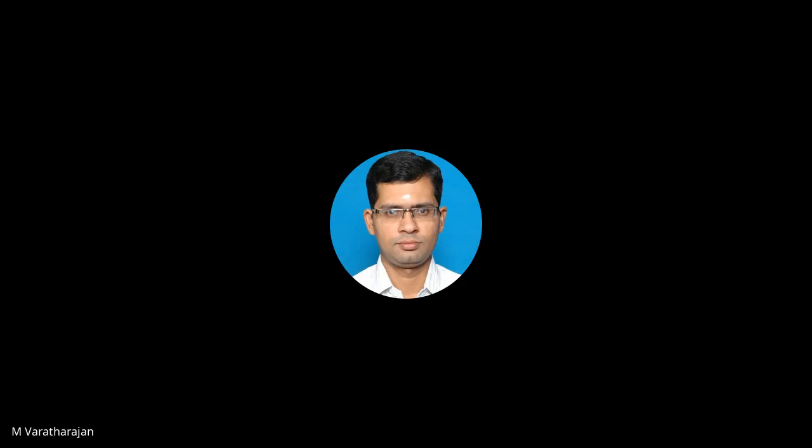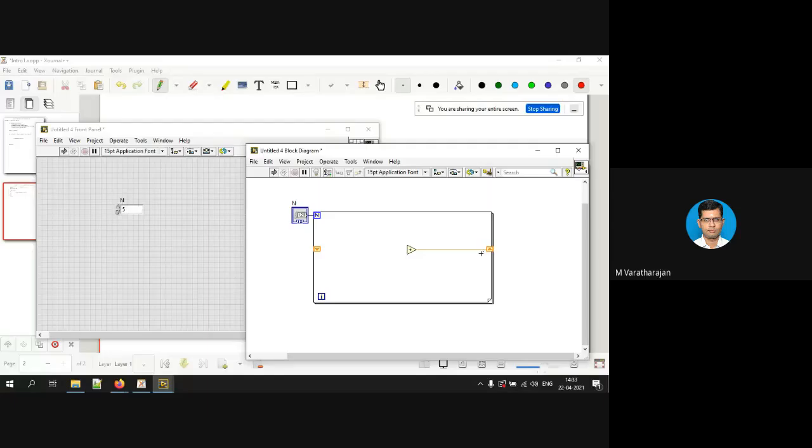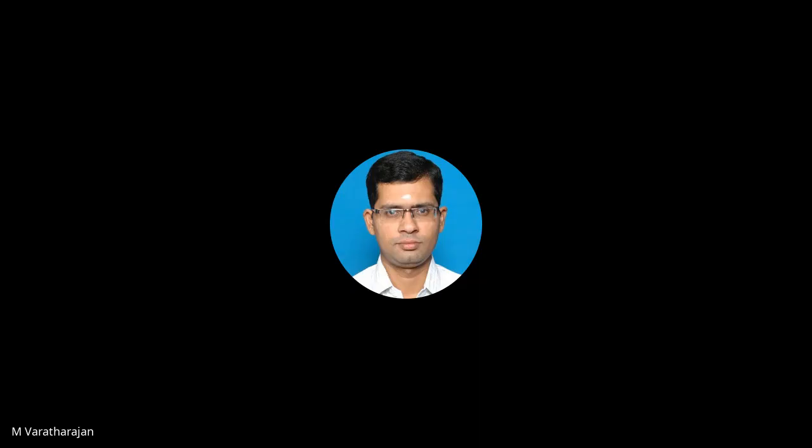As a first step, connect the output. That is our sum of present iteration. As per our logic, sum of present iteration is sum of previous iteration, that is whatever you have taken from left hand side, plus another number. That is our iterator. And as per our program, initially we have put the sum value as 0. This you can put in the left hand side. On the left hand side, right click, create a constant, that value is 0.